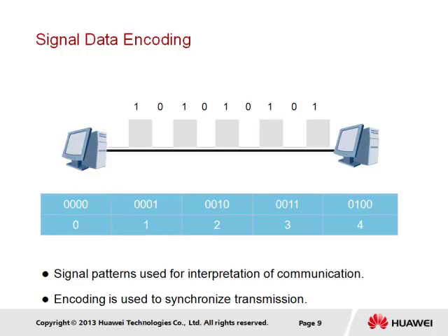Signals over Ethernet are defined by voltage to represent two states of 1 and 0 that can be interpreted by the receiver based on patterns in the transmission. Together with the fixed rules for synchronization, known as line encoding, sending and receiving entities are capable of handling data communications over the transmission medium. So different rates of transmission require the use of different line encoding standards to synchronize clocking and ultimately ensure the transmission can be successfully interpreted once the signals are received.